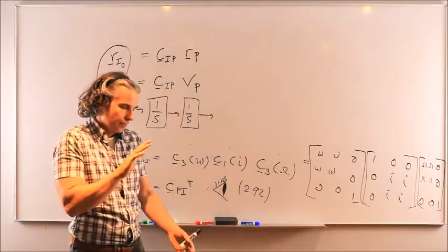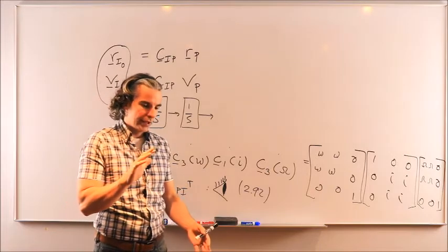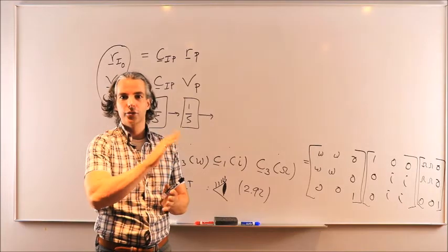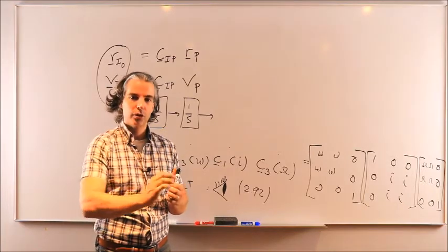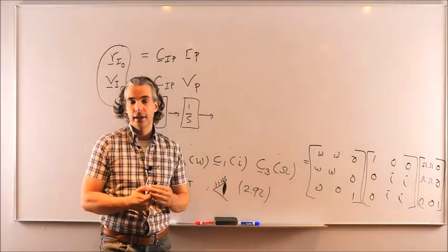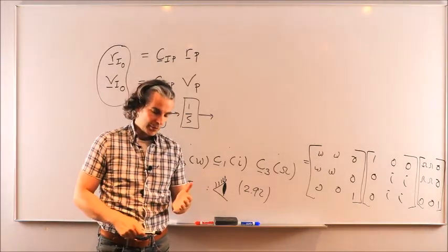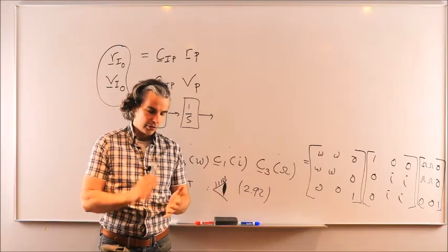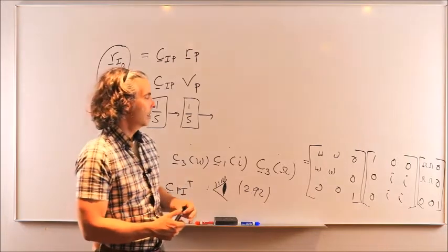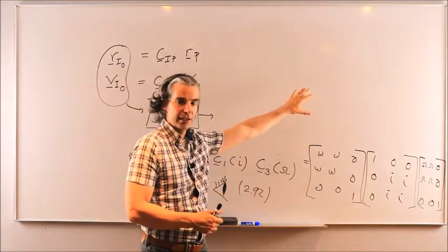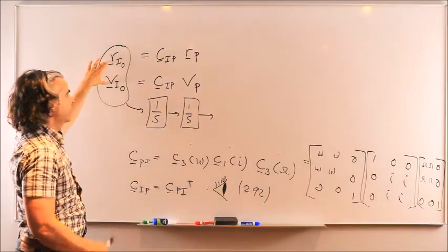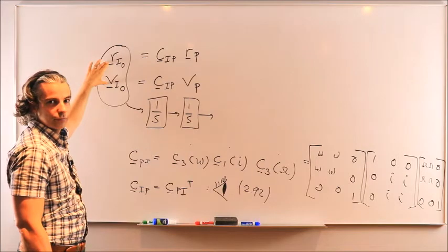And from that base point of view, we then defined all the angles we needed to orient our orbit in 3D space, as well as to locate the spacecraft along the orbit. We did that through the use of 6 classical orbital elements: semi-major axis, eccentricity, inclination, RAAN, argument of perigee, and time of perigee passage. And then we saw how to practically turn those 6 classical orbital elements into position and velocity at any time we desire.